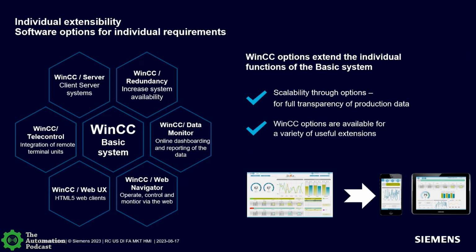And we've got a unique way of doing redundancy that is just a little checkbox. So when you design your project, you say, hey, I want to make this redundant. I check it. I identify a redundant server. WinCC will do all the back end work there to create the package and deliver it to the redundant server, and you're ready to go.